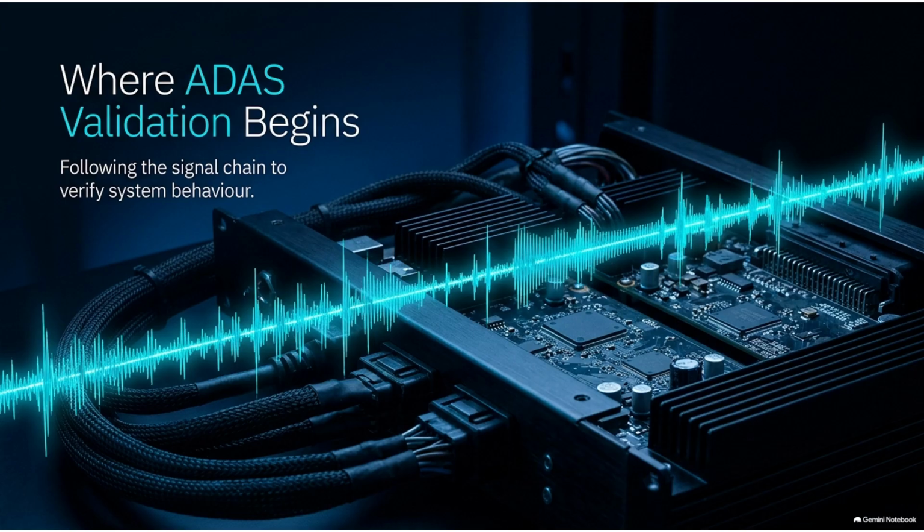When we test an ADAS system, we cannot just look at the vehicle computer, the ECU itself. ADAS behavior is a team effort. Sensors detect things, the network sends the data, the ECU makes a decision, and the car reacts. Professional validation means we follow this complete signal chain to verify how the entire system behaves. Our main job is to prove that the whole chain works correctly under control.